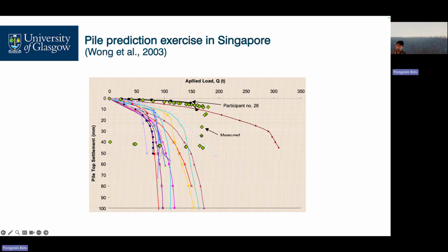Exactly the same layers of soil, same diameters, pile lengths, and exactly the same loading steps. Then you can compare your load settlement curve and load transfer curve, and superimpose. Oh, hey, my numerical modeling looks very good because my FE results catch up with my pile test results.